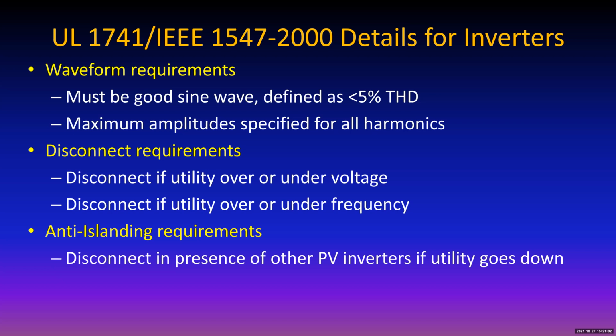So this is a very important concern here, and utilities have had a lot of concern about it. But so many experiments have happened now over the years that it's well documented that the anti-islanding requirement works so well because the inverters act as current sources that are necessarily synchronized by the utility voltage, which if it's lost, they lose their synchronization and they go off frequency and they quit.